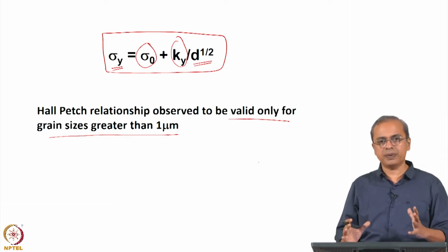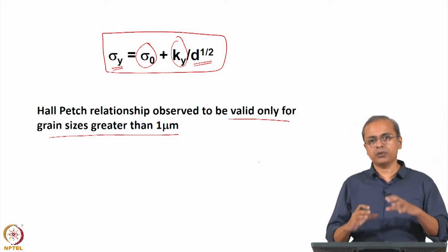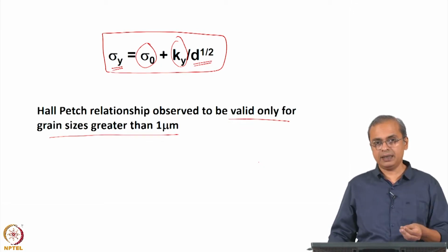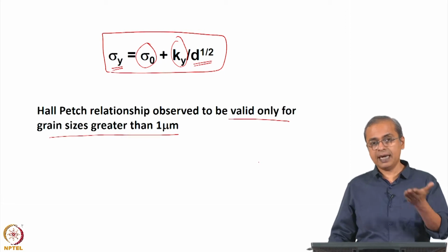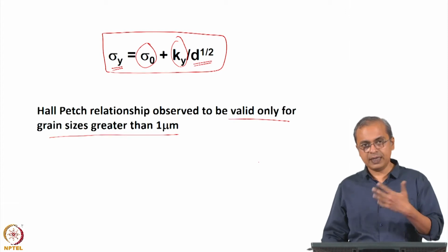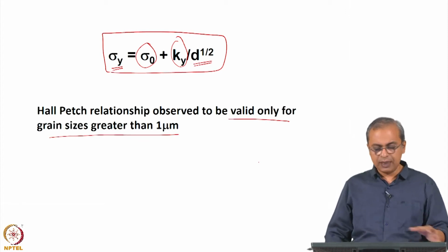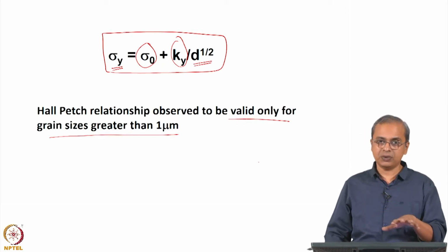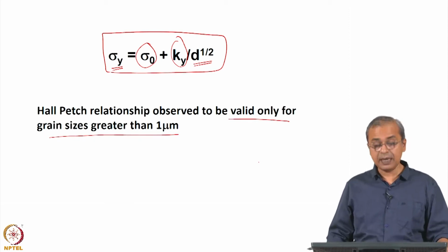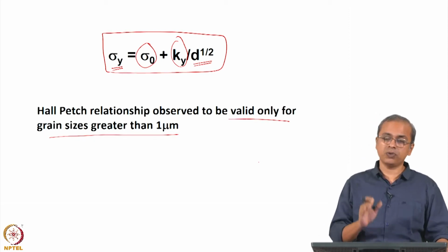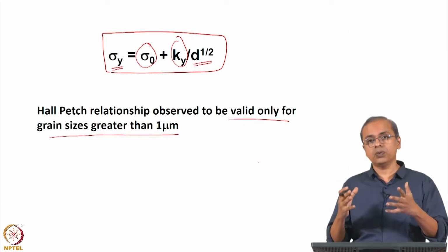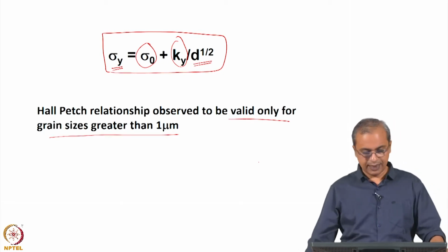But that is the Hall-Petch relationship. It is a very important contribution by itself to the field of material science, because a lot of the treatment of materials so that they will have the kinds of properties that we desire in a final product, which relate to cold working, reducing the grain size and so on, are related to this understanding that if you reduce the grain size, your yield strength will go up. Therefore, this is a very important relationship, and any deviation from it is also very important for us to recognize and to understand, and that is the idea of this activity.